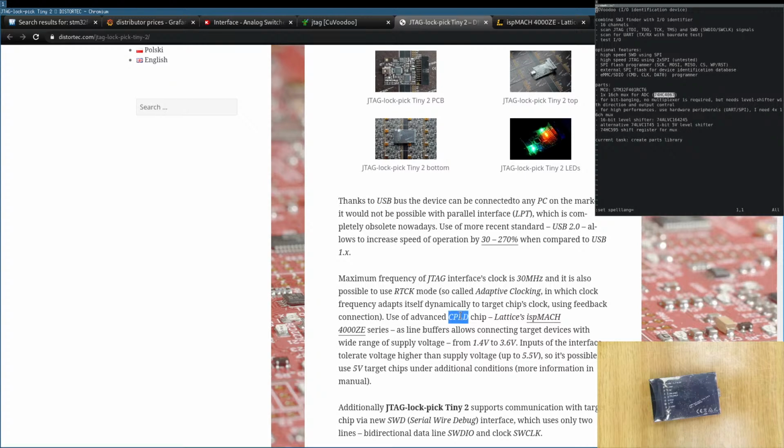And what this allows you to do is kind of like a switching matrix. You can define which pin on the input goes to which pin on the output, and so on. And the advantage of this one is it operates from 1.4 volts to 3.6 volts, and it is 5.5 volt tolerant, but it is not 5.5 volt compatible, meaning that the input pin supports 5.5 volt and it will be recognized as a high. Now the output pin will still be at 3.3 volts maximum or 3.6 volts maximum, and you have to be sure, I think it is written somewhere,